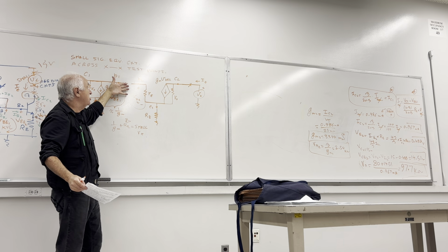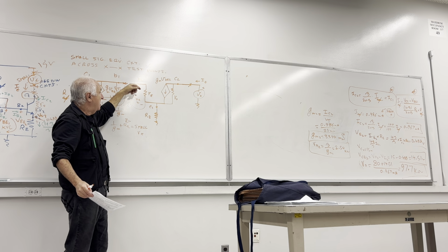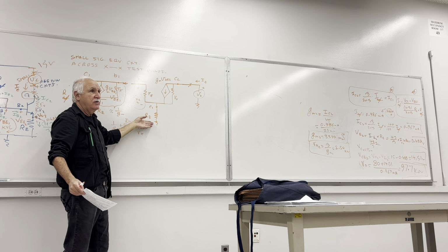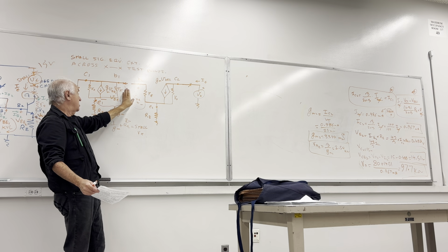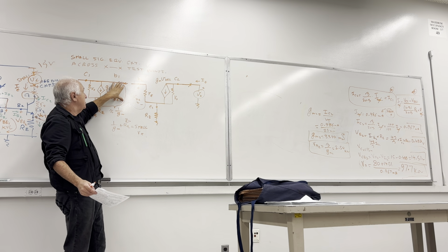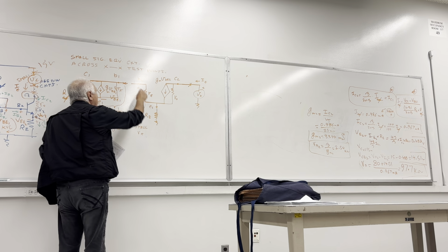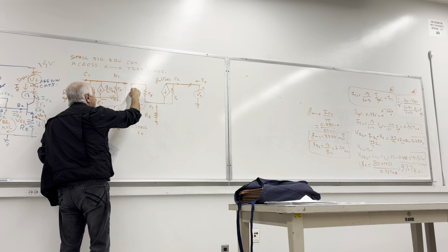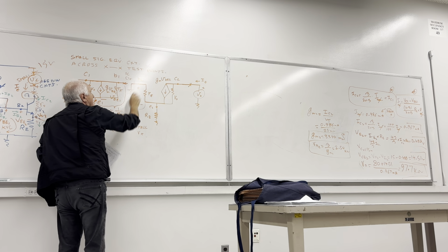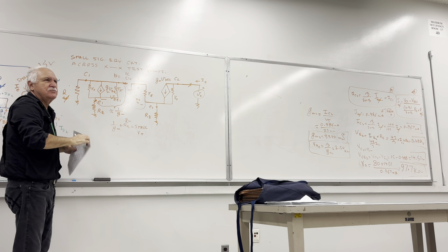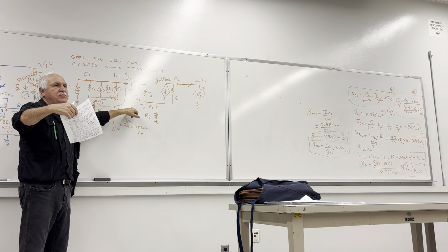On the other hand, impedance looking in that direction is awfully high. It is R pi plus 1 plus beta times this RE. So giant input impedance, very low output impedance to the left. So as if this impedance shorts that impedance from that terminal. Therefore, we will imagine that this is really connected to ground, 0 volt approximately, and this doesn't count. It will simplify your analysis considerably.